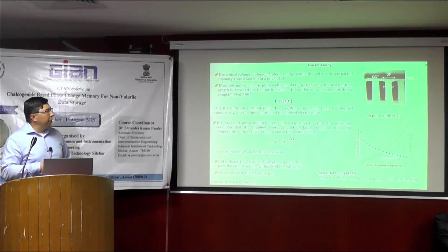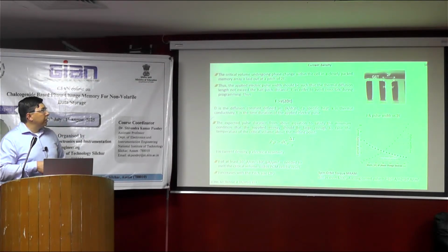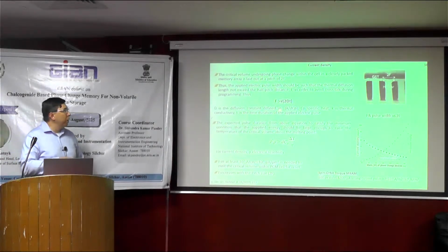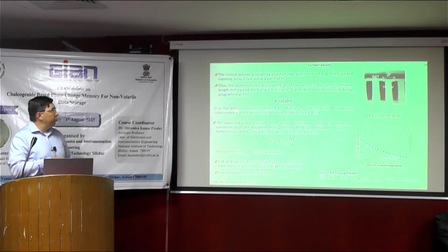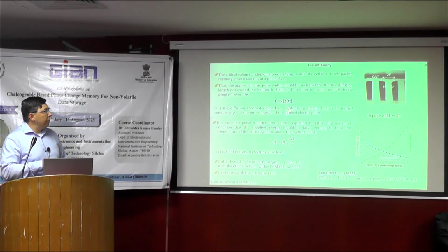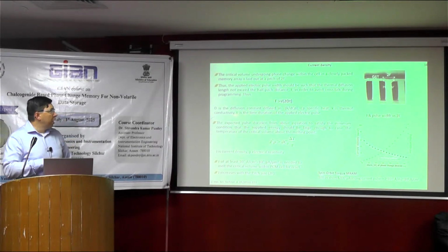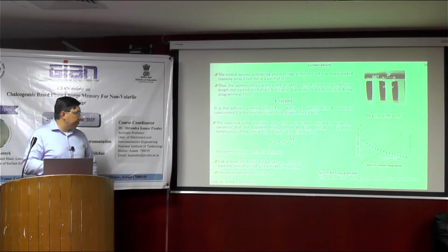So in the technology, the distance between two cells is defined as 2F. This F is called the footprint. According to this, to avoid crosstalk between the cells, this F should be larger than the square root of 2Dt. D is the diffusion constant, defined as k divided by dCp, where Cp is the specific heat and k is the thermal conductivity, and t is the time duration of the applied electric pulse.